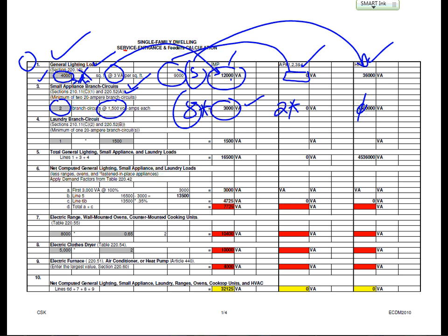Based on the NEC, the whole apartment is going to have 8. So you take 8 times 1500 volt-amps. For each apartment it is going to be 2 times 1500 volt-amps. For the common panel, what is it going to be? 0. Why 0? There's nothing there. Is there a common kitchen? No. Any comments, guys, about the small appliances circuit before we leave it?